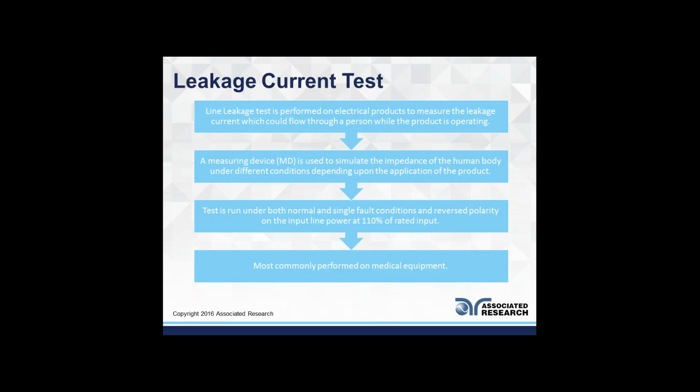This test is required on the majority, or actually all, of the medical equipment that's out in the field. The point being that the medical devices do come in contact with patients, and they're also more stringent about the line current test, or leakage current test, sorry. There are also more tests required, more than the leakage current testing, but in medical devices there are a lot more tests involved when you're testing to different points of your device, different applied parts, and we're measuring all the resulting leakage current to all these points.